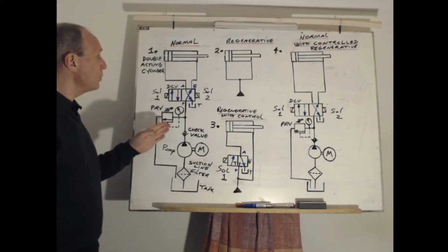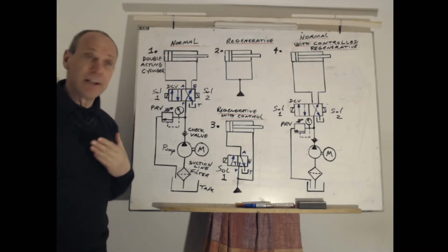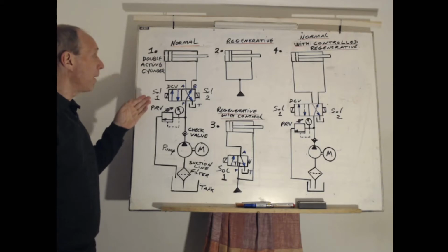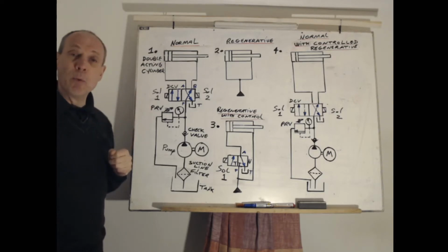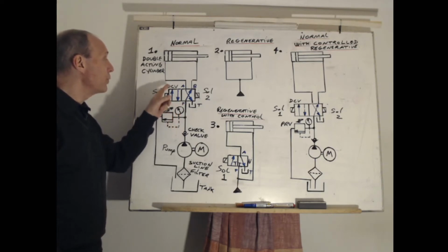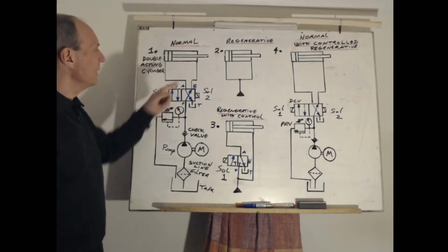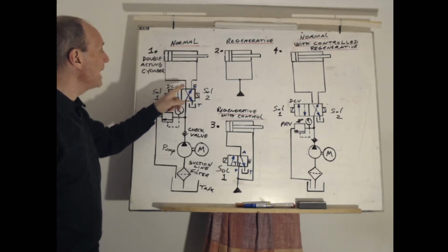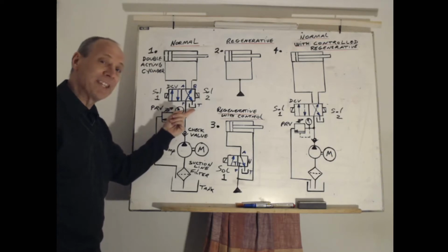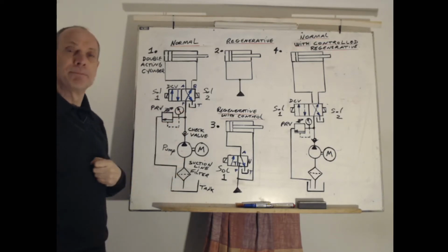The drawing shows that the flow is going into the cylinder and causing the double acting cylinder to be in the retracted position. Of course, if we applied an energised solenoid number 1, the valve would go across and oil would go up, through, into this side of the cylinder, and this cylinder would go forwards. Of course, the oil here would come down, go through and return to tank. This small symbol of the tank is really the return line going back to the main tank.